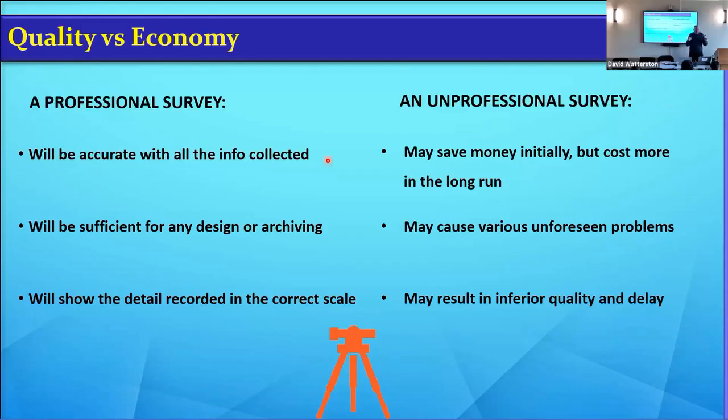If you ask for the grid intervals, then when you put it on a CAD system, you can check that that grid interval is what the computer tells you, and you've scaled it correctly. Once you get that scaled correctly, then you can get Google Maps, put that on top of that, scale that up, and then you've got a visual and some line work that you can rely on. Then when you go to site with your client and you're discussing what you're going to do, you can take a few dimensions to make sure how good is the Ordnance Survey digital data.